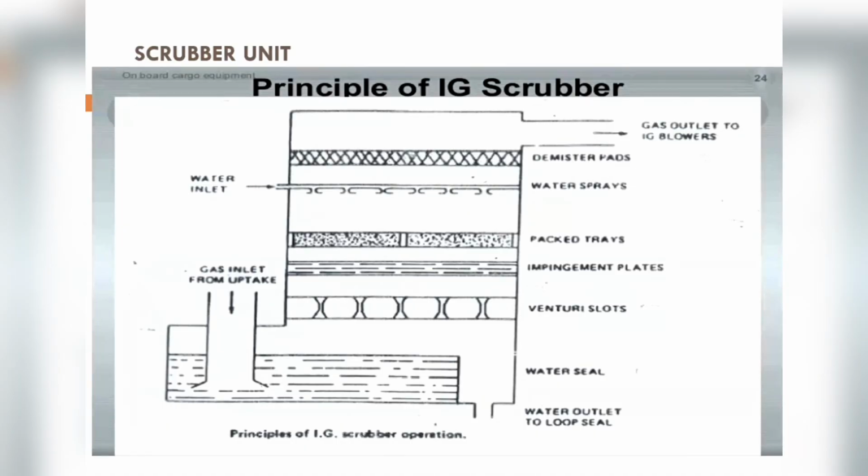So in those cases, the scrubber tower is just cooling it. Maybe it's getting heated and it's just for precautionary sake passing through the scrubber tower for cooling purposes, which also does not require. So in such cases, when there is a requirement that you cannot pump out the scrubber tower or something, you can avoid using it, or you can circulate the same water for cooling purposes. But when you have this kind of system where you're using the uptake from the boiler, this soot has to go over water. You cannot avoid it.